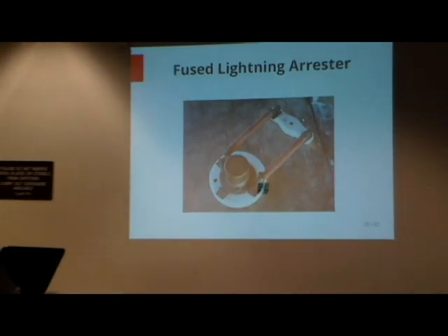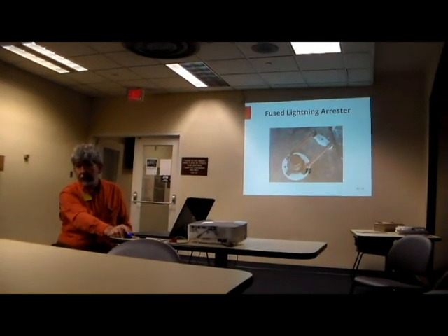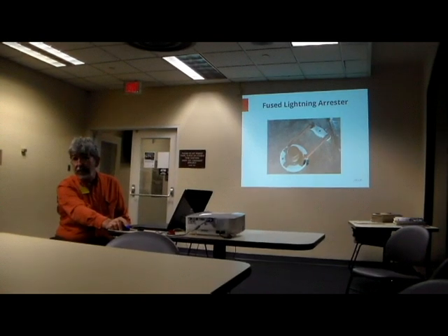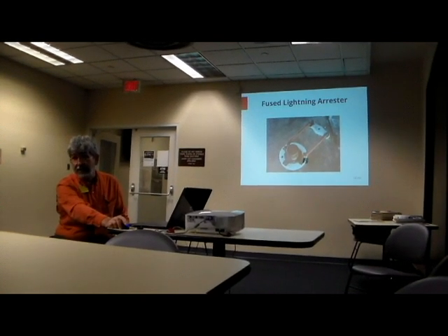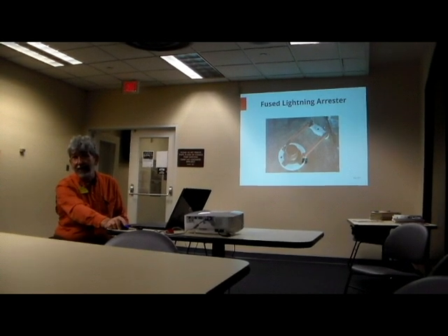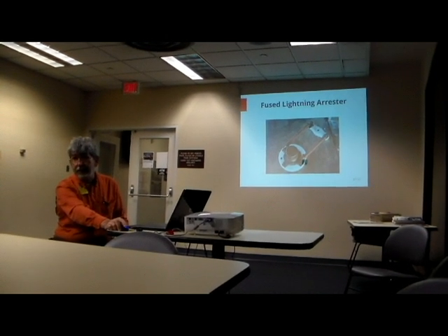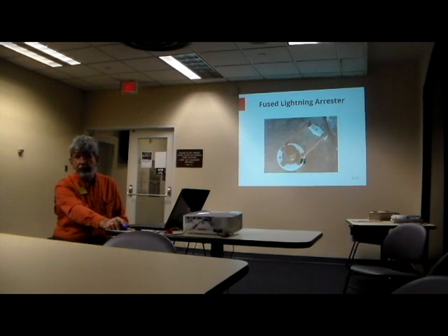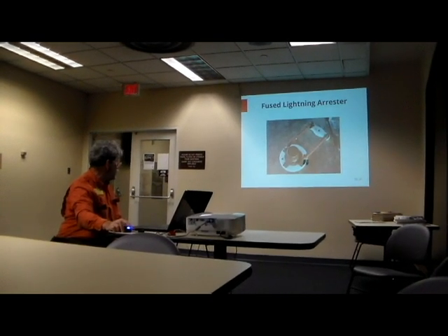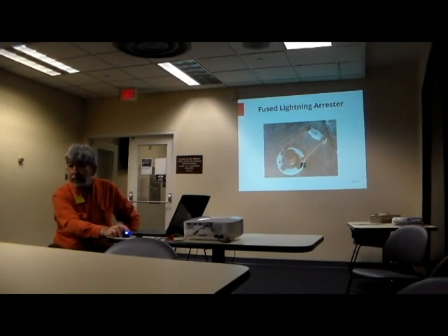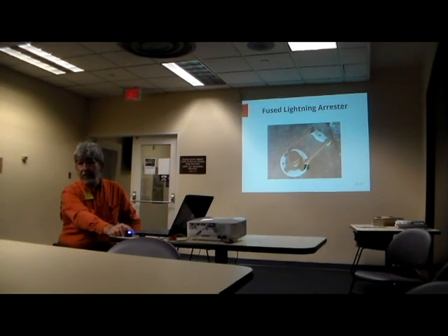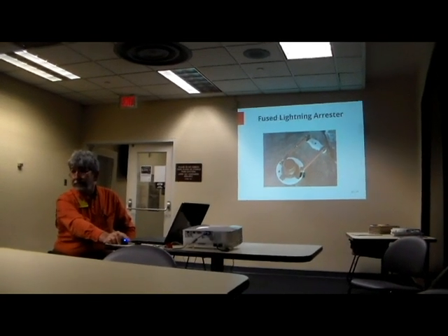Because if you broke that line with a fuse, you took the whole line out of service in telegraphy. In telephone practice, you only take a single customer out of service. So that's why you could have the fuses in the main line in telephone, but not in telegraphy. It was not tolerable, so they were used the other way around in telegraphy. And the fuse was for when things got rocking and that line lit up like nobody's business. It at least was less likely to set fire to the place.